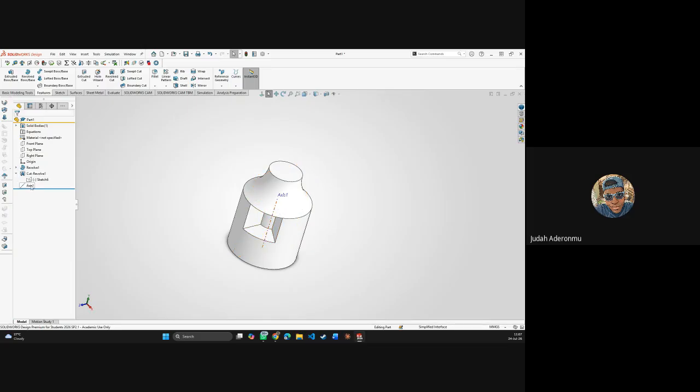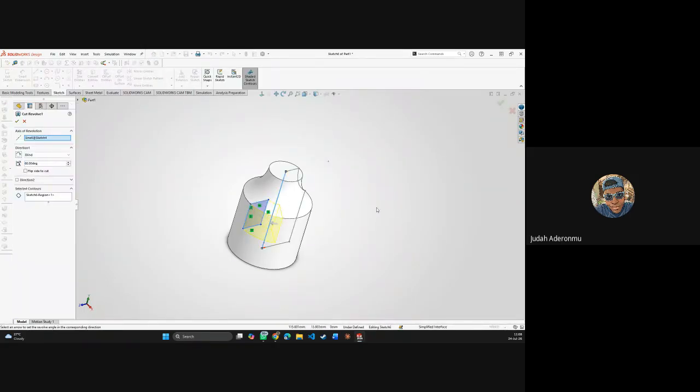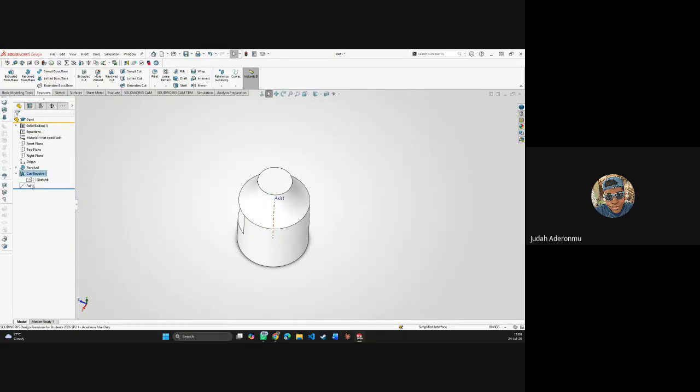So in this particular case now, okay, you know what? I'm going to drag the axis to before I did the revolve cut. It's a cheat code. Because if I had left the axis, let me show you something. Right now, if I click on edit, I've already created the axis, but the axis is not showing because in my timeline, I created the axis after I did the cut revolve. So I cannot reference the axis inside the cut revolve when it was done after the cut revolve. Please, I hope you understand what I'm trying to say.